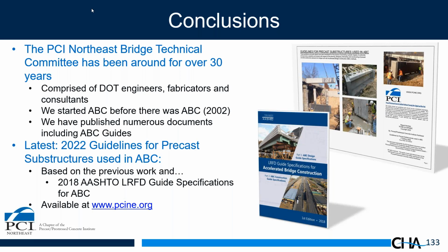Okay, next question, Mike. Any issues with key joint between precast cantilever abutment regarding temperature variations, especially in Nordic regions? Yeah. Well, the key thing is we've detailed joints that are filled with grout and joints that are not filled with grout. And we have notes in those first 5 or 6 pages that talk about if you want a true expansion joint between two pieces, you can fill the void with a foam, a sprayed in foam, to allow the structure to expand and contract.